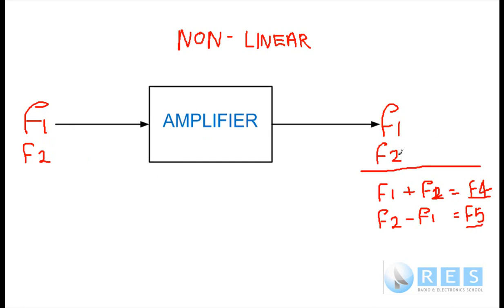This is a very important method. All you need to remember is that if you have a nonlinear amplifier, there are other products, by the way. These are called mixing products, because when you have a nonlinear amplifier, you have mixing going on in the amplifier. And when you use an amplifier deliberately to mix, it's called a mixer, and we'll be talking about that shortly. This amplifier is indeed a mixer because it's nonlinear, and if we put two pure sine waves in, we'll get two pure sine waves out, or pulses out.